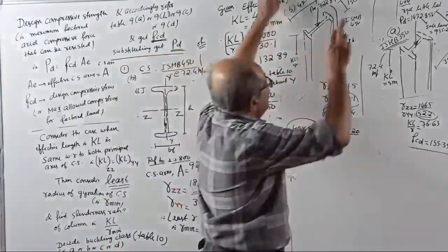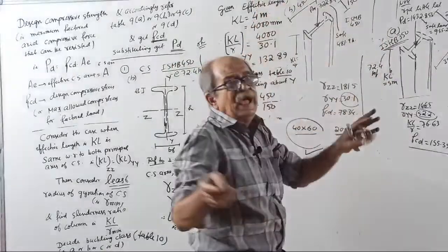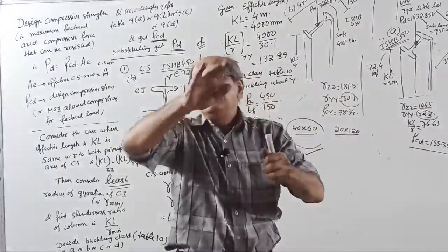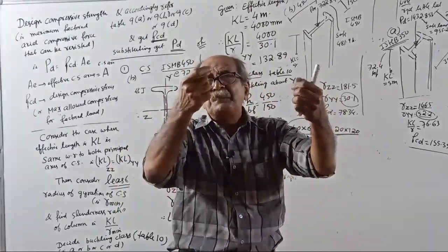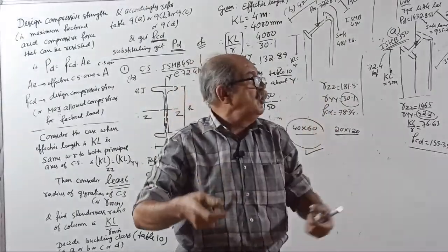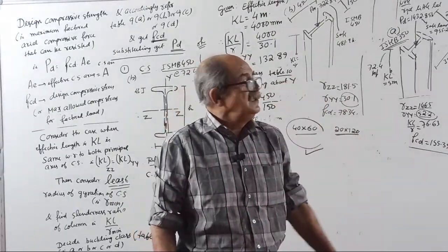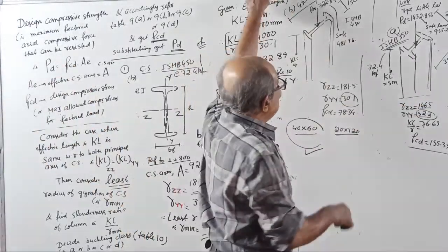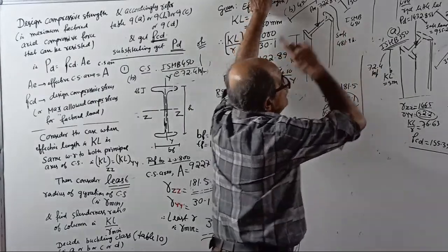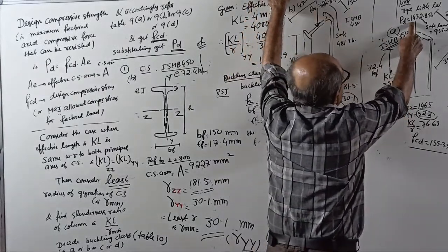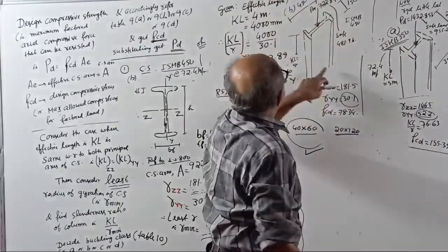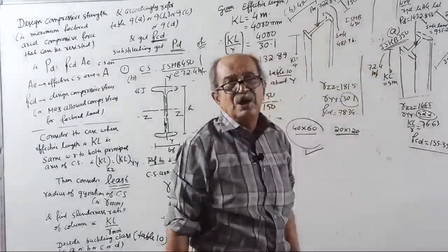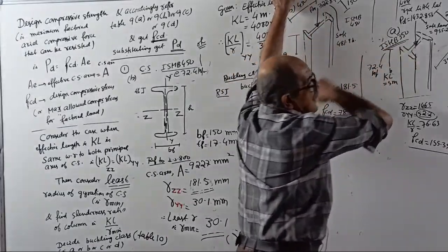Therefore here, see, both the columns are of the same material, same length, same cross-sectional area, same weight. Money also same. Both have the same price. You pay 20,000 rupees for that one. This also 20,000. But because of the sectional arrangement, this column capacity is 1,432. This column capacity is 722. Almost half. Yes or no?